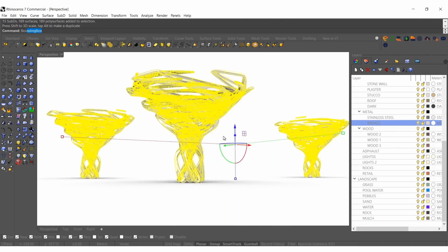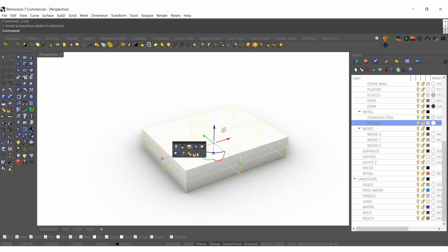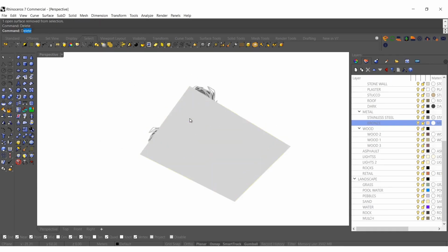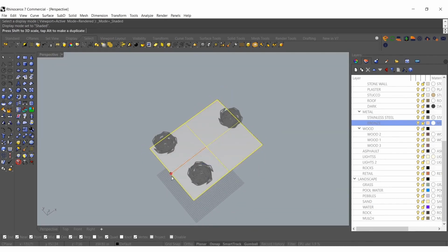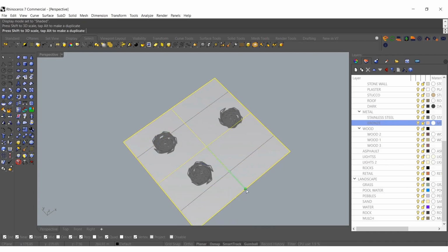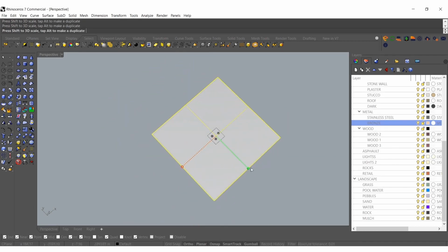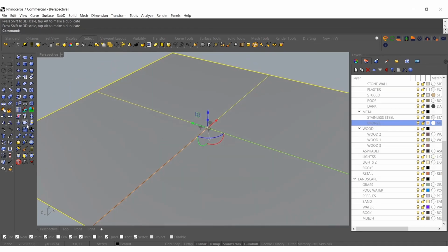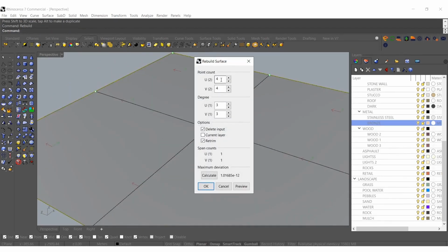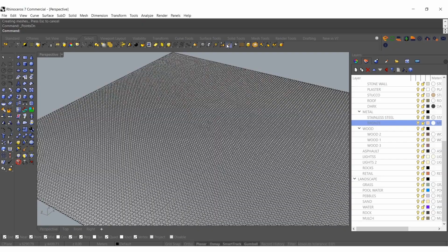Okay, and then we'll just make our landscape now. I'm just going to walk down the models we just created, explode out the bounding box that we just did. Okay, I'm going to go to shaded, try to capture a majority of these. And these are going to be, let's just make them really tall underneath the tree canopy. So our landscape would be relatively simple. So I'm just going to type in rebuild surface. Let's do 125, 125.